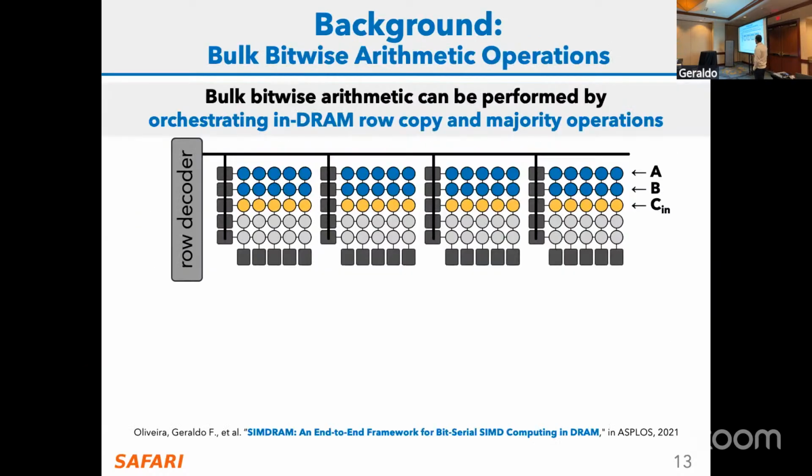So, okay, we started very simple. We start by doing in-DRAM row copy and in-DRAM majority. But what about something more complex, such as an addition or a multiplication operation? So in the SimDRAM work, we show that we can generalize this framework or these operations to compose more complex operations using a 3-step framework, which Onur already mentioned. I'm just going to illustrate how that framework actually operates.